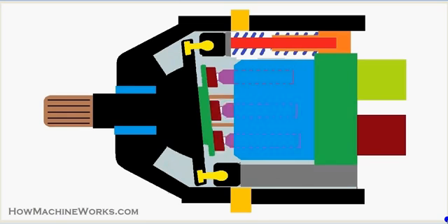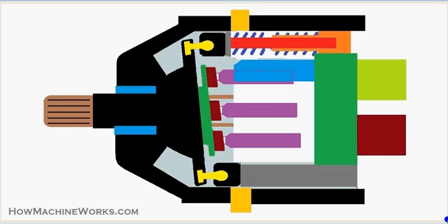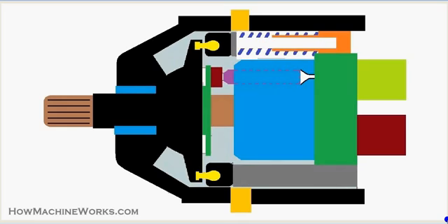So we have more number of pistons arranged. You can see when more pistons are arranged, the top pistons are moving towards the back as per the swash plate angle, and the bottom pistons move towards the front due to the same angle. So I am releasing the pressure as a result of this. The swash plate becomes vertical. So when we have a vertical swash plate, at 90 degrees, there is no flow happening inside an axial flow variable displacement piston pump, but it becomes variable according to the swash plate angle when it increases or decreases.